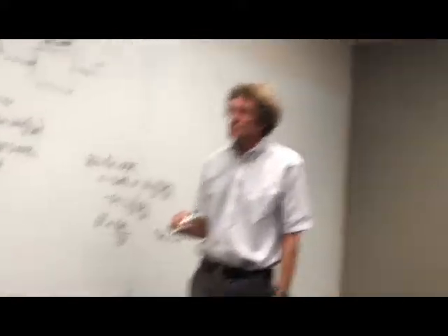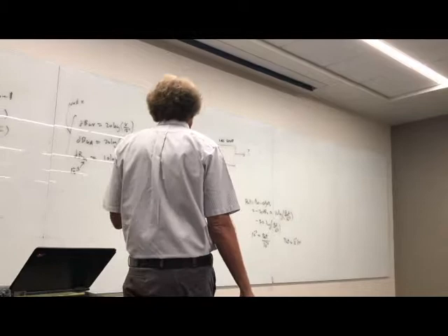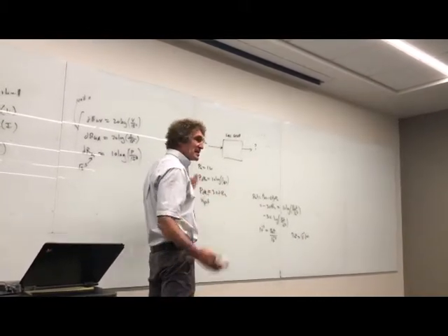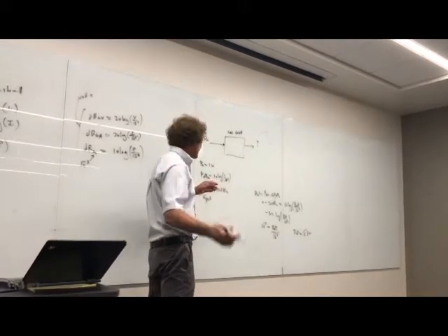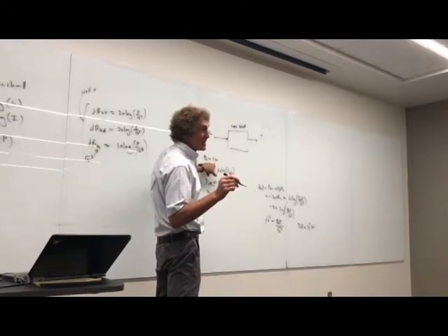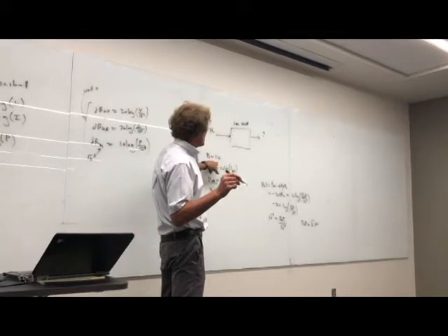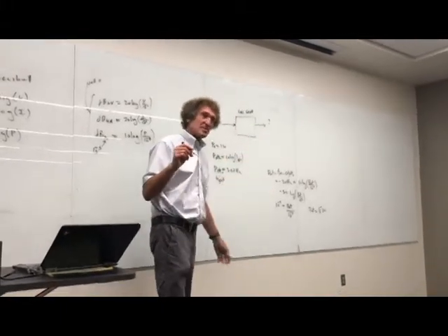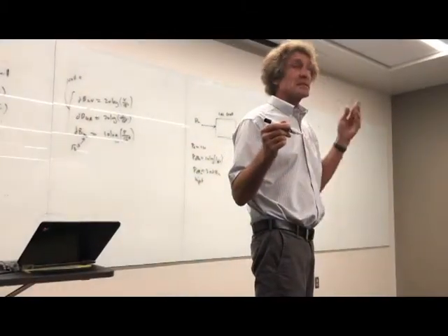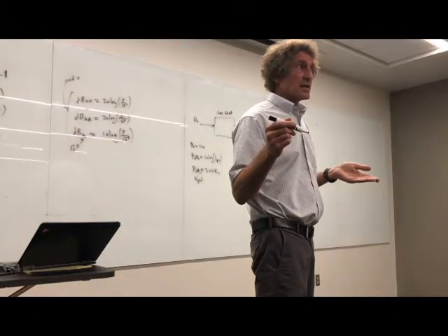One thing you can almost pick up on right now, no matter how many dB, here it's 60. 60 dB means, is it 6 orders of magnitude less? Well, if I got 1 watt going in, 6 orders of magnitude less is going to be 10 to the minus 6, correct? If it was 30 dB of loss, I would have 10 to the minus third coming out. If I have 100 dB of loss, I would have 10 to the minus 10th coming out. Follow me on this, class? All right, so that's dB in a nutshell.